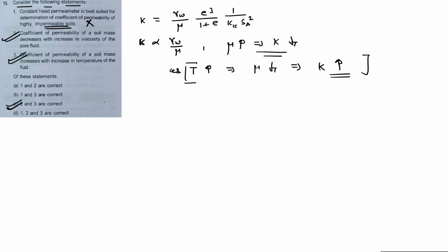So through this question, we will try to understand how permeability depends on other factors like particle size, effect of void ratio, effect of permeant like its viscosity and temperature, shape of the particle, degree of saturation, effect of soil fabric, impurities in water, effect of absorbed cations on clay minerals, and effect of effective stresses.